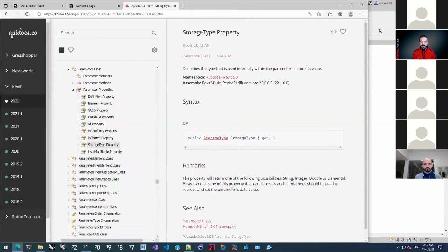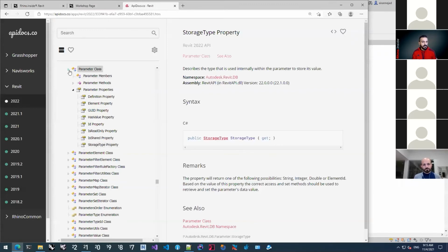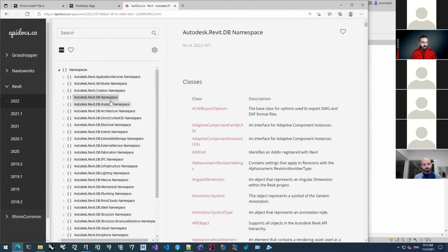So this is the easy, short description of what the Revit API is. I showed you the differences between DB and UI, showed you there are sub namespaces for different disciplines. We talked about the differences between UI application, UI document, and the DB.Element that represents everything. Anything that's available on DB.Element is propagated through all the derived classes, so it's available to all of them, just like any other object-oriented programming language.